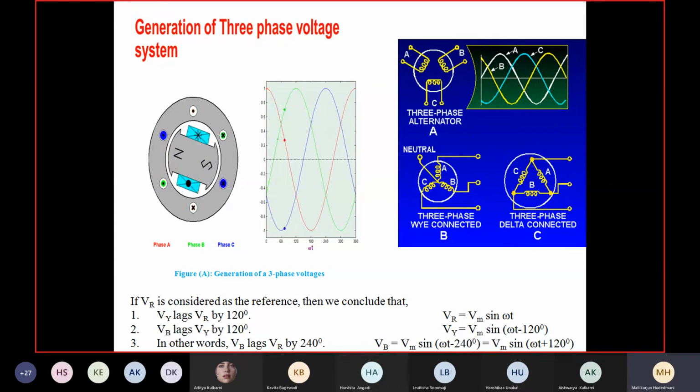So whatever the naming, there is a perfect phase difference of 120 degrees in a three-phase system. We should have a common exchange of identification, because it matters whether a machine has an RYB phase sequence or an RBY phase sequence. That is called the phase sequence. Phase sequence is the order in which the peaks of the waves occur.